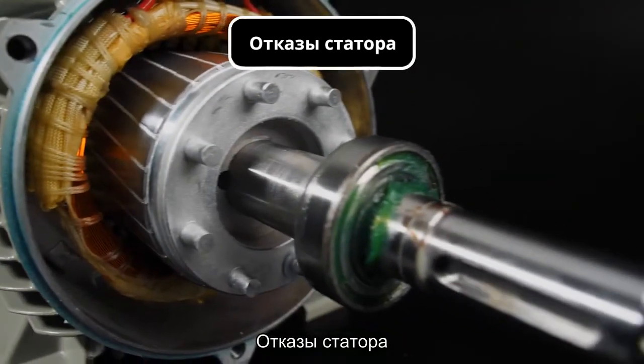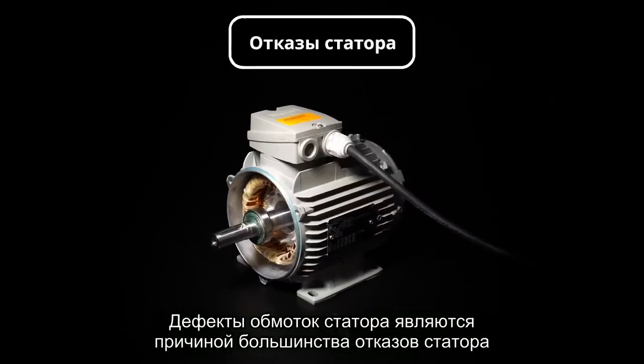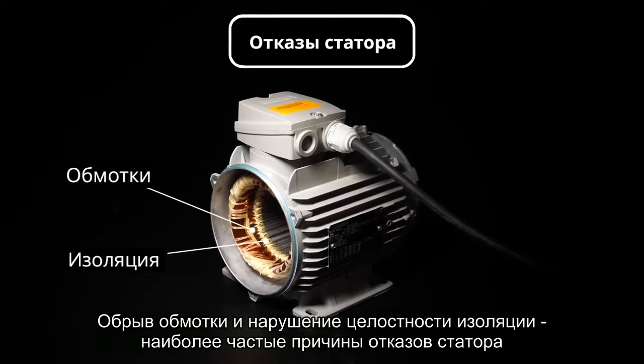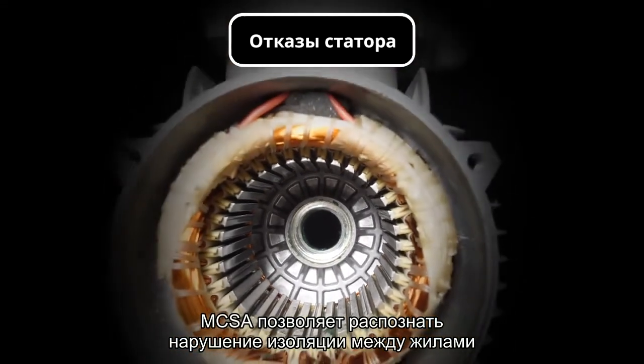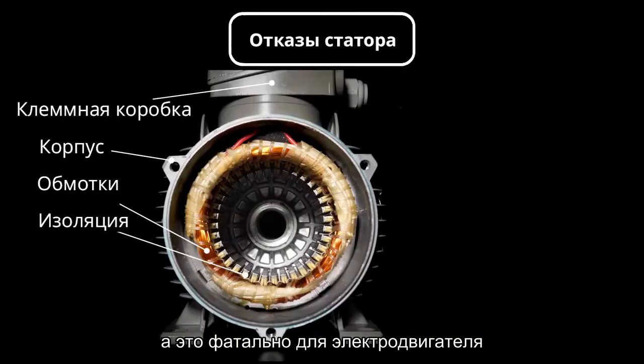Stator faults. Stator winding faults cause the majority of problems in stators. Broken winding insulation is the most common stator fault. MCSA can recognize broken insulation between threads, which can lead to broken insulation between phases, and it is fatal for the motor.